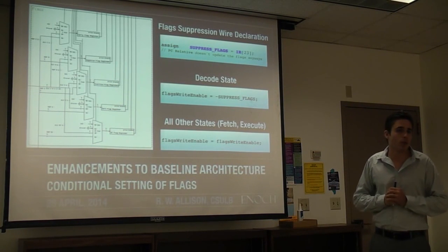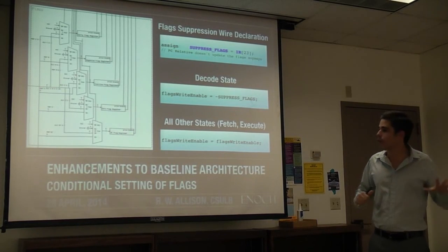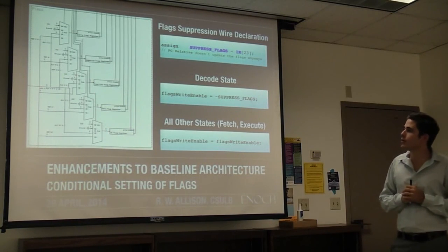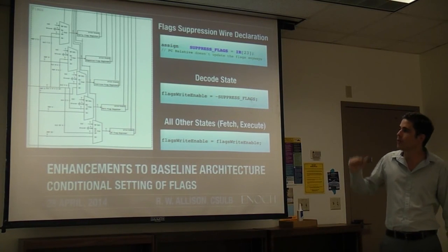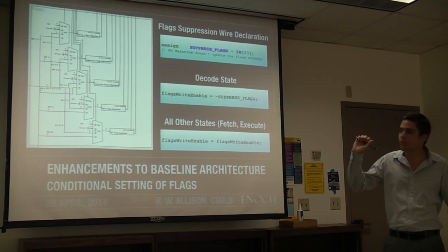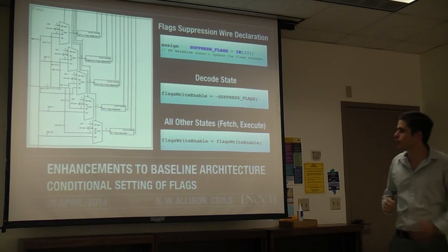So thus, with one control signal, we can turn off all of our updating of flags, so it just gets the previous value. And then we have the ability to either set the flags by loading VCC, clear them with ground, and then take either flags from memory or our ALU flags. And that's all done with 2-bit concatenations of 5 different values right here.